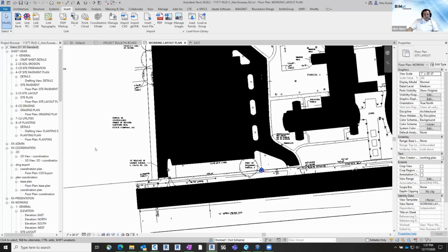So yeah, there's multiple ways to get to this end solution. The key is just doing it early on in your project. You want to make sure you get that set up early. It just makes life a lot easier. Exports coming down from Revit for civil engineers, we can just bring it in on 000. Same thing, you can bring in the updated layout file into Revit later, and it's going to drop in where we want it to. So setting it up early is the biggest key.